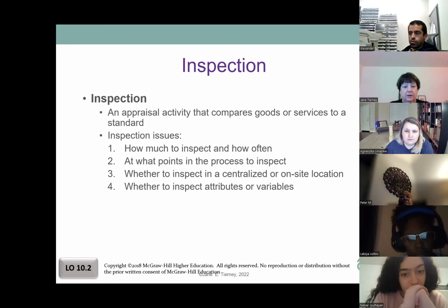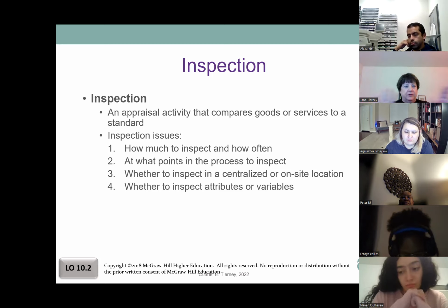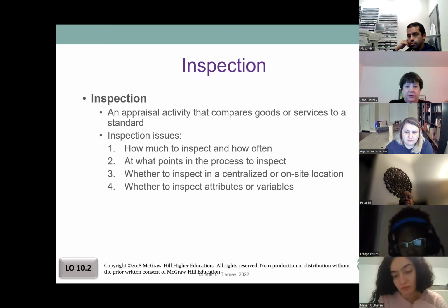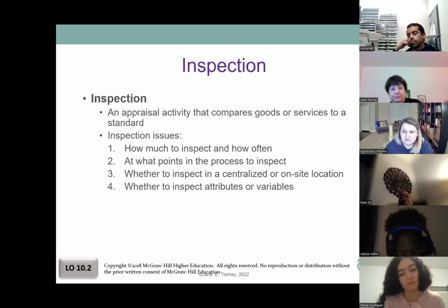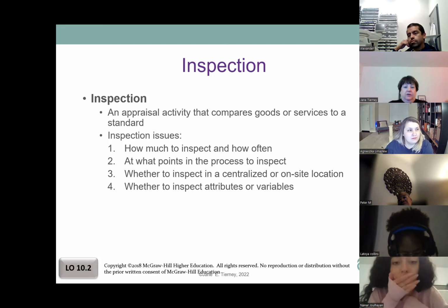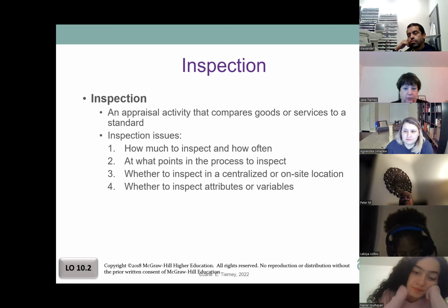Inspect before. Before what part, Peter? Before the drywall. Why? Because electrical needs to be up to code. And you can't see that if we put the drywall up, right? We can't see what's back there. So if we put the drywall up, all we see is a wall. We say, oh yeah, that looks really good. But we can have the wires all going the wrong way and everything upside down and wrong. And so no, you can't put the drywall on until you've had the electrical wiring inspected.